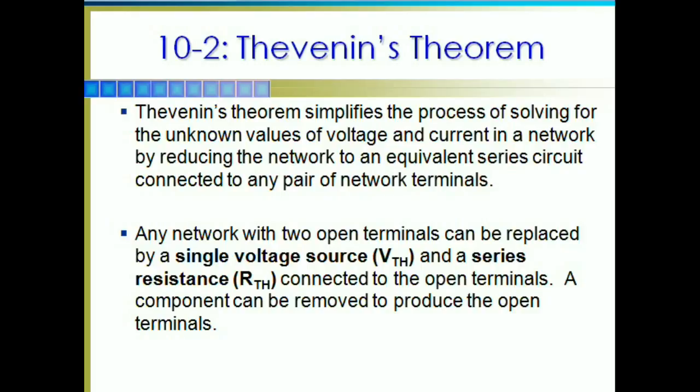Now, Thevenin's theorem simplifies, as it says here, the process of solving the unknown values of voltage and current in a network by reducing the network to an equivalent series circuit. Basically, it's going to allow us to create a voltage divider that we can then vary the load on and easily analyze the effects of the load, as opposed to having to do a full set of calculations every time we change the load. So we can do one set of calculations and then apply those to different loads.